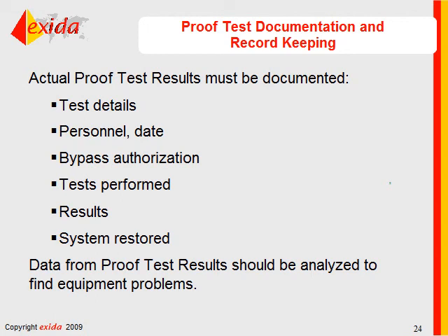It all depends. When you perform your proof test on a block valve, the question is, what is the objective of the block valve? If it's just to stop flow and you can tolerate a certain amount of leakage, then arguably there's a certain amount of failures that you don't necessarily need to detect in order for your safety instrument function to be successful.